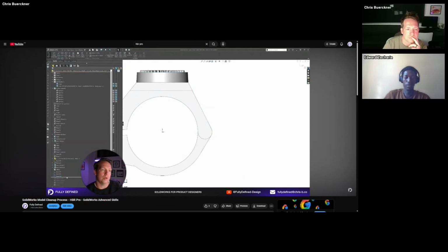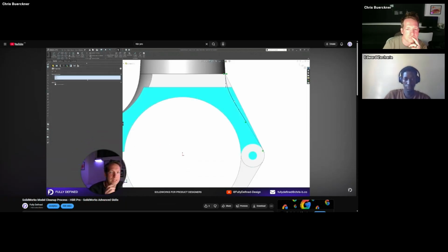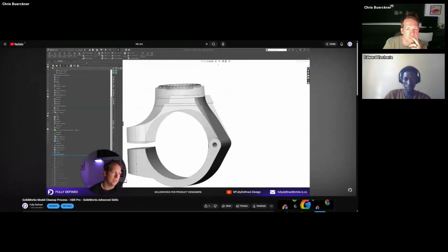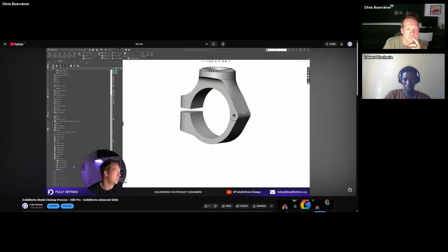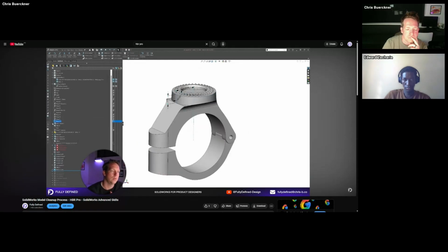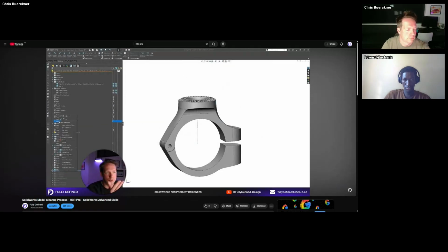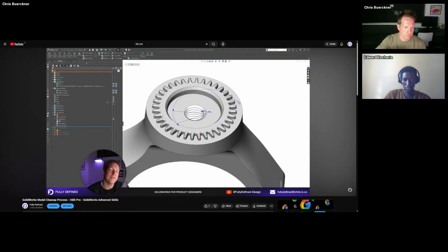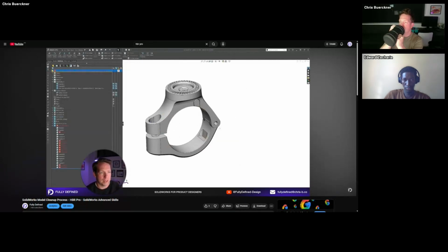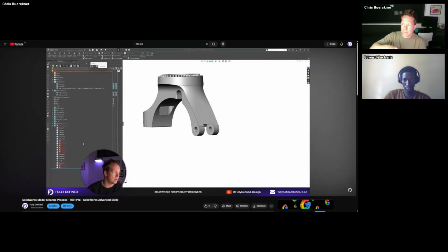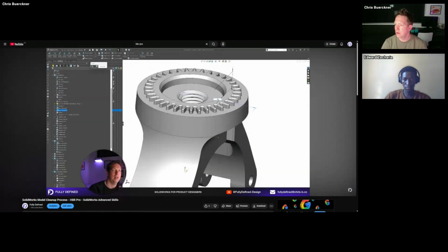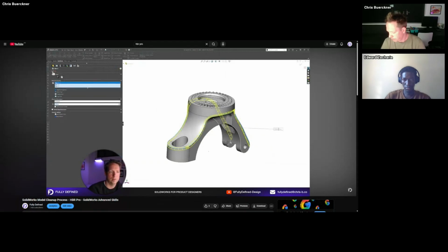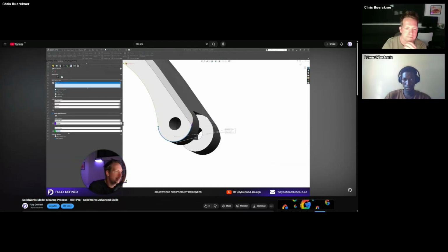My goal now is to bring all of the key driving elements back to a singular driving sketch at the top of the feature tree. Some of these elements are planes that we use as sketch references. My preference when I'm sketching is using sketches as sketch references and have it all in one drawing. To replace those planes, I created new sketch elements in the driving sketch, then updated the feature references to refer to that sketch rather than the original planes. Once the references changed, I could go back and delete those planes.